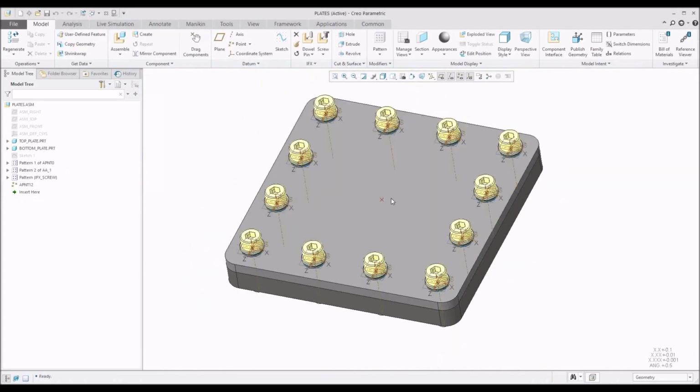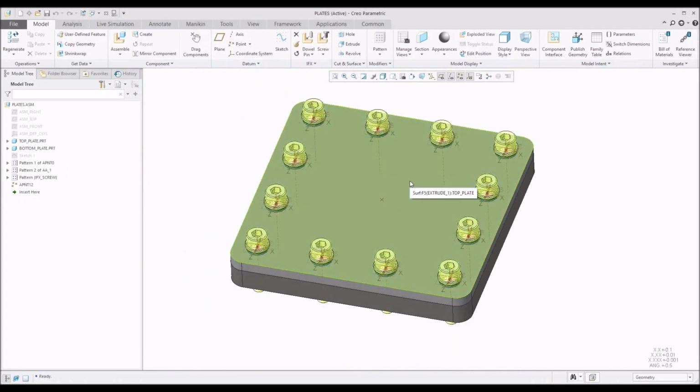One of the other things I want to show you is, if you guys have been using Creo for a while now, you know that as soon as you use a normal pattern, you pattern your points or your axis, as soon as you assemble something to that pattern, it will use a reference pattern and assemble everything that was assembled to one of those pattern members. So one of the nice pattern tools is a point pattern. That's when you want to have different dimensions and bits and pieces for that. So you can use a sketch for that.